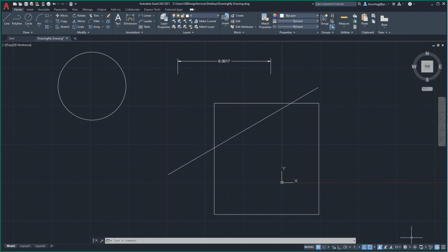The next icon to the right toggles the annotation monitor on and off. The annotation monitor displays a yellow badge on dimensions that have lost associativity. For example, the locations at each end of a line segment that a dimension string was originally referenced to have become disconnected from that dimension string.